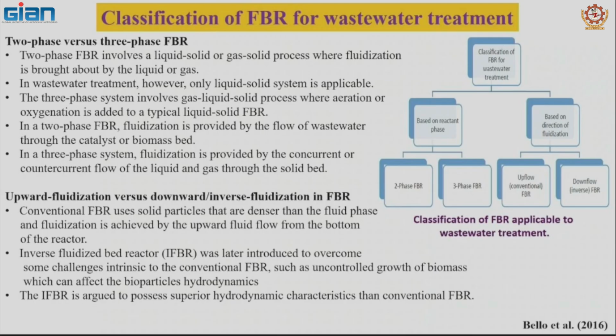But the inverse fluidized bed reactor was developed later to overcome some of the challenges of the conventional fluidized bed reactor, where an uncontrolled growth of biomass affects the bioparticle hydrodynamics, that means wash out of the bioparticles from the bed.